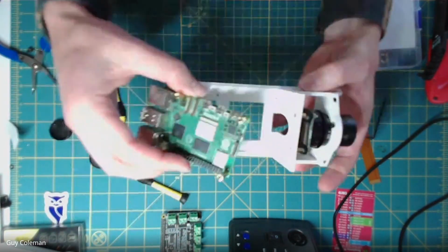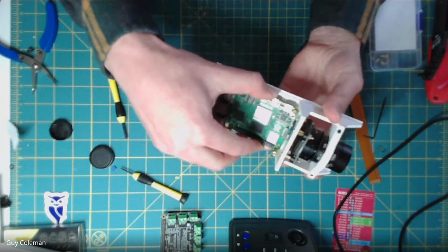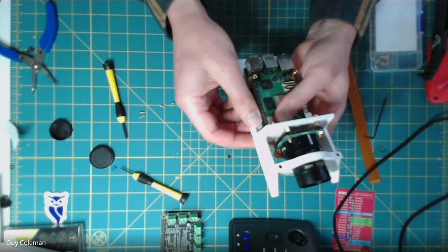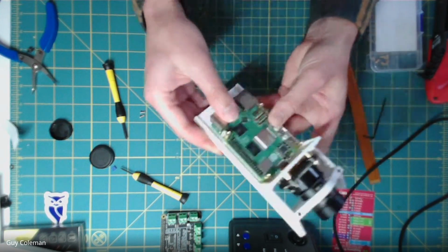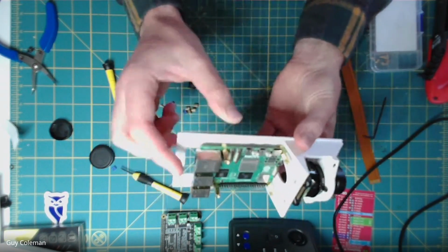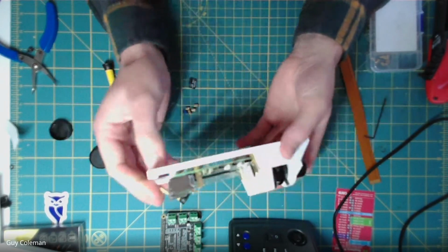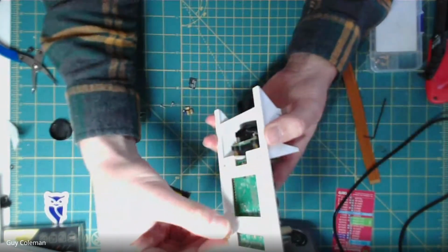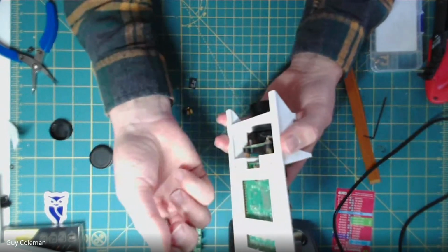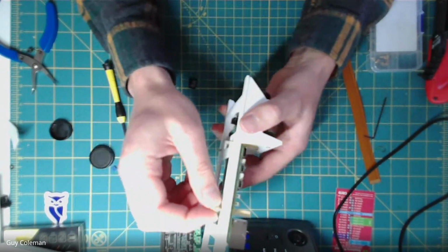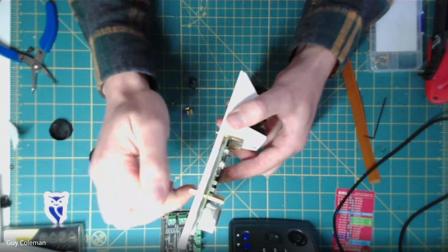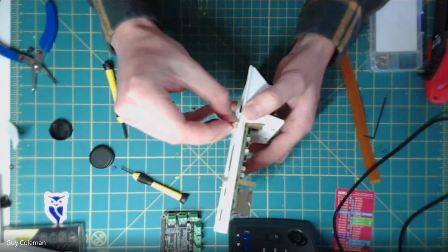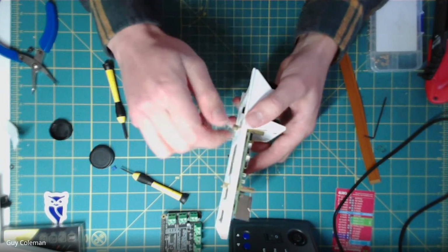But first, we'll put this Raspberry Pi in. That should fit in there like that. Make sure the outputs for the USB and Ethernet are at the front. And then you can use either, of course, nuts, I guess. I like using the actual brass standoffs because I think you get more grip on the thread and they can tighten down a little better. So I put those on.